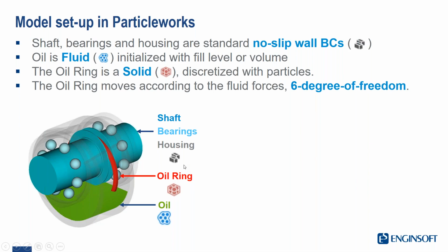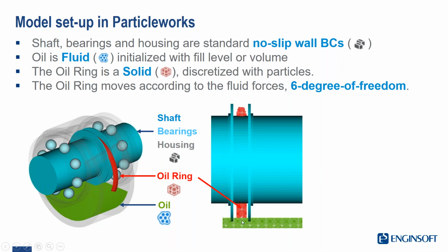Differently, the oil ring element, as you can see, is assigned to the solid material that is possible to assign in Particle Works. This means that the oil ring is discretized with particles in the same way the fluid is, and this aspect, the fact that we discretize this solid material, enables the coupling between the fluid and the solid. So basically, on this element, we didn't include any kinematic law, but we just let it interact with the